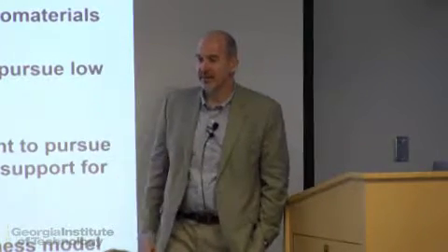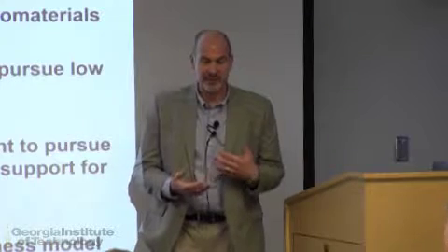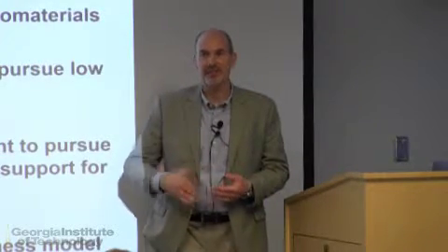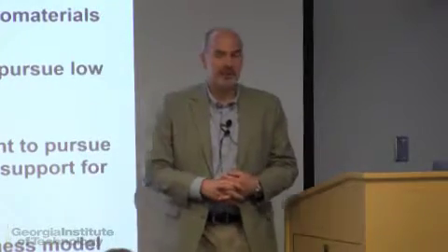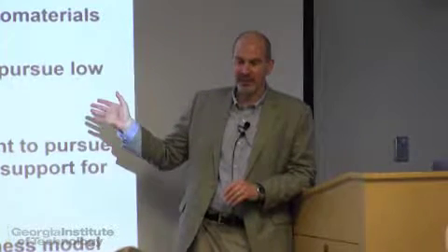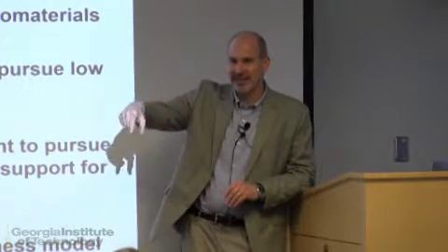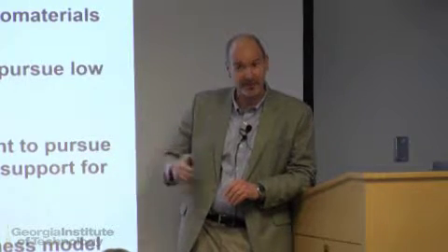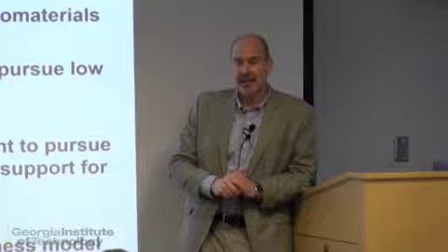3D printing, compared to a lot of manufacturing technologies, gives you a little bit more variability in the outcome. When the FDA looks at processes, they want you to validate them to show that every time you give the same input, you get the same output. I think that's difficult to do with 3D printing. There are actually variations, for example with the laser sintering process, the position in the build platform in which you build the device creates some variability in the device.